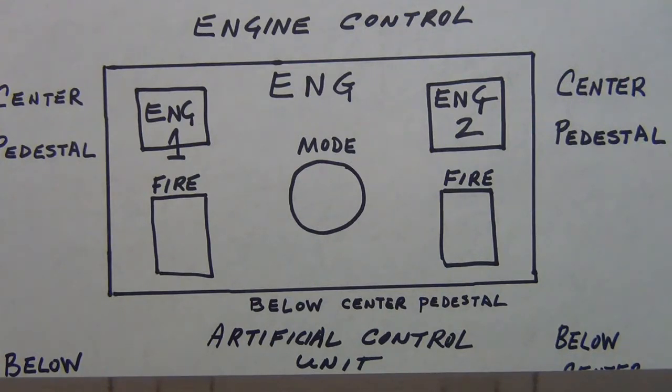Okay, so dry crank means what? Dry means not with fluid. So when you're selecting that, on the ground, it's not opening up the fuel shutoff valves, so you don't have fuel flow in that position. Does that make sense? Dry crank? Okay, so that's what's happening there.